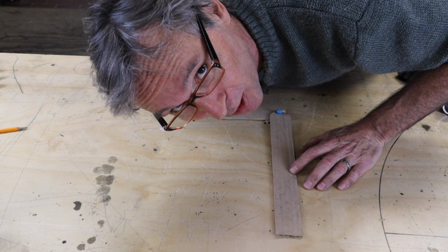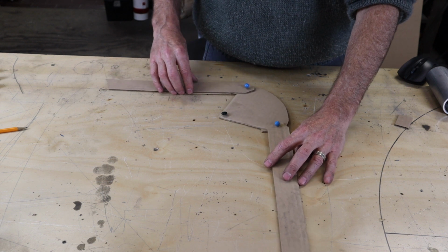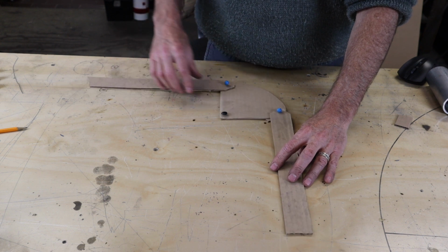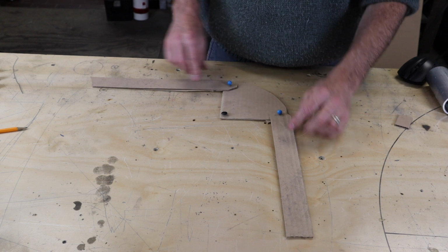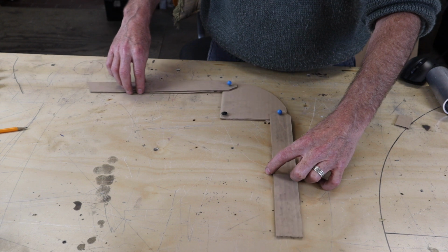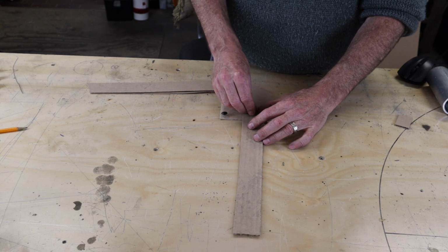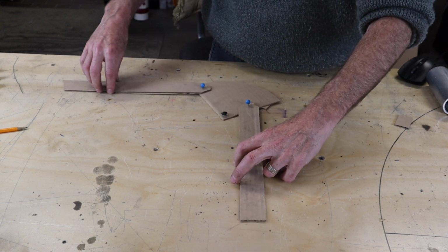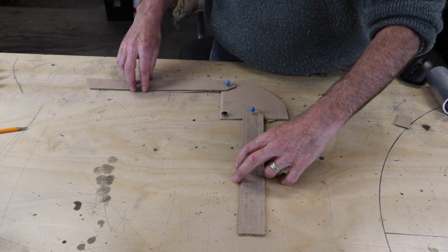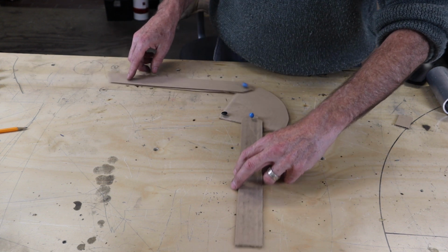So this is a bell crank. So named because it was used to ring bells in the servants' quarters when a rope was pulled. And you can see it has a fixed pivot point and two moving pivot points, and it changes the direction of the motion from vertical to horizontal or vice versa. And by moving the pivot points, we can change how much work is being done. So now we have a lot of movement here and not much movement here, but more force here. And we could obviously drive the other way. We could have a little bit of movement and a lot of movement on this one.